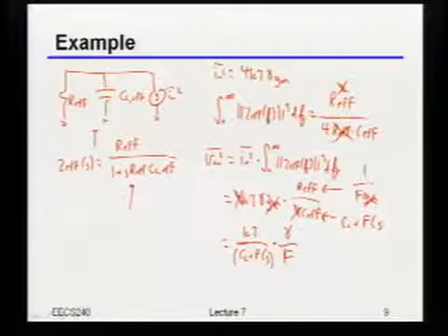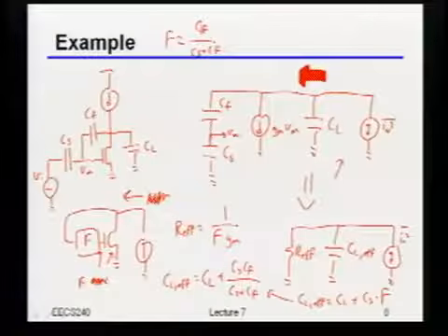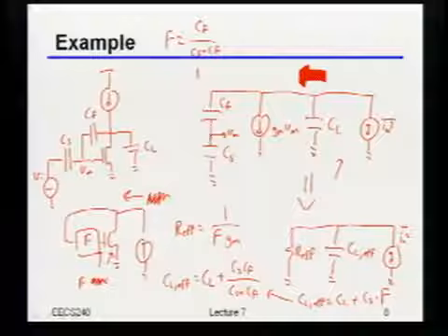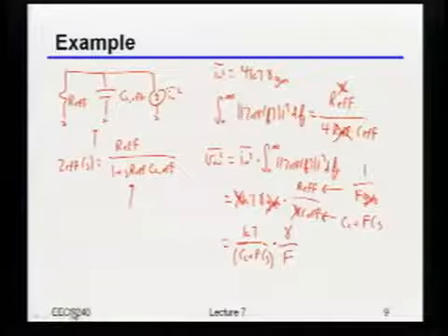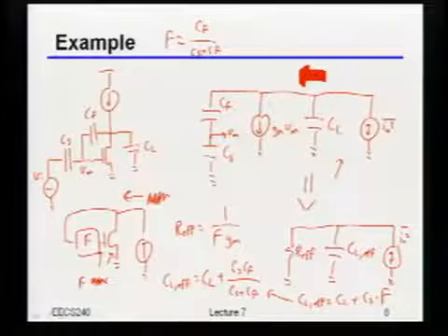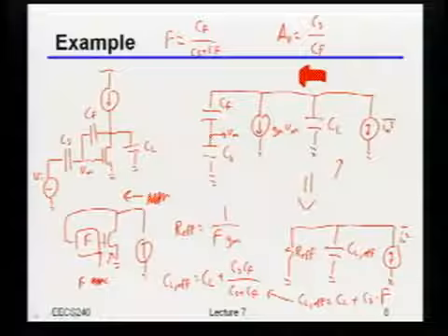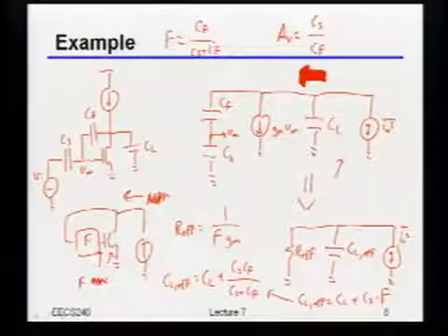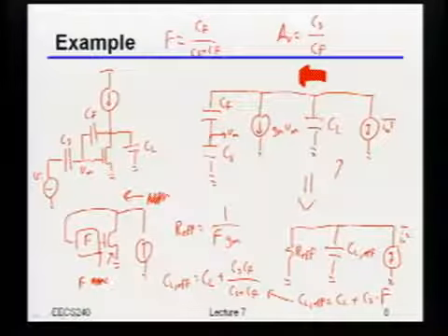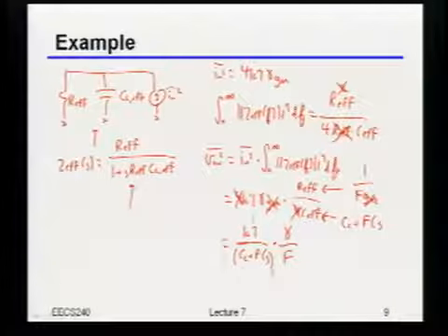And notice this F right here, just as a reminder, that F is CF over CS plus CF, is not exactly the same as the gain, because the gain is again just CS over CF. Right, so just like before, because we were changing the source impedance, we're actually amplifying the noise up by some factor. Okay?